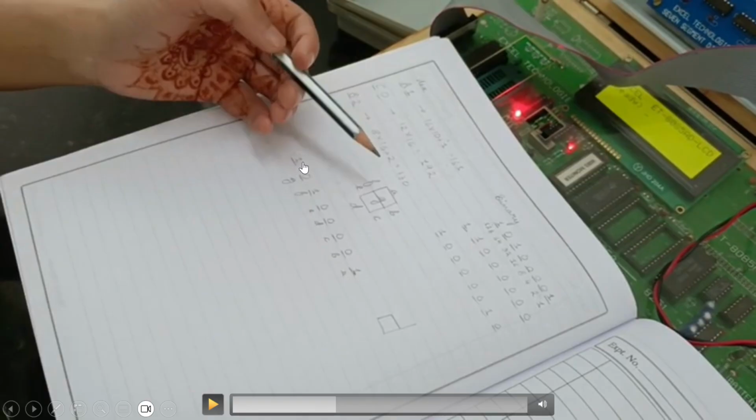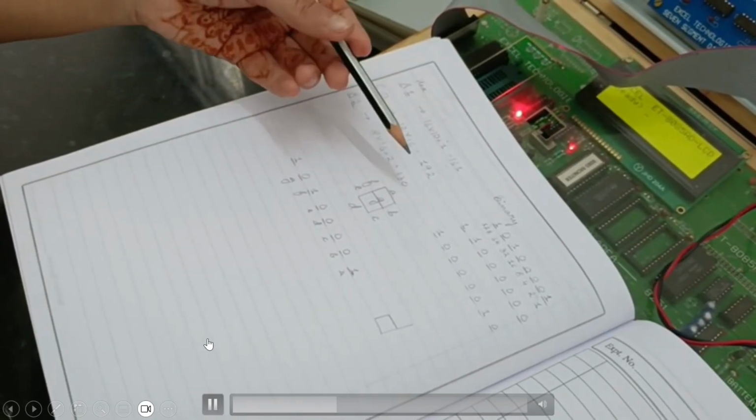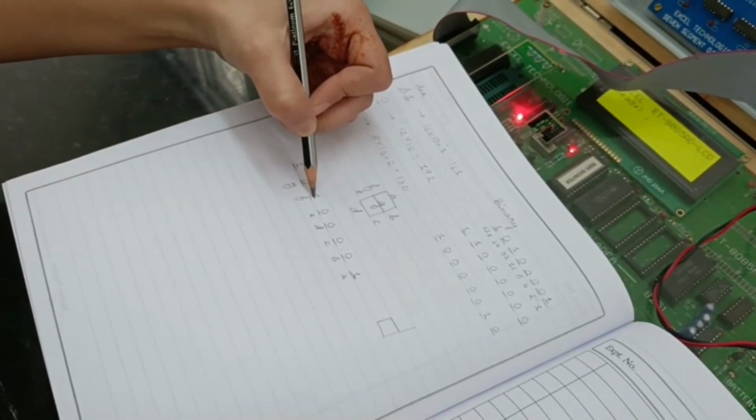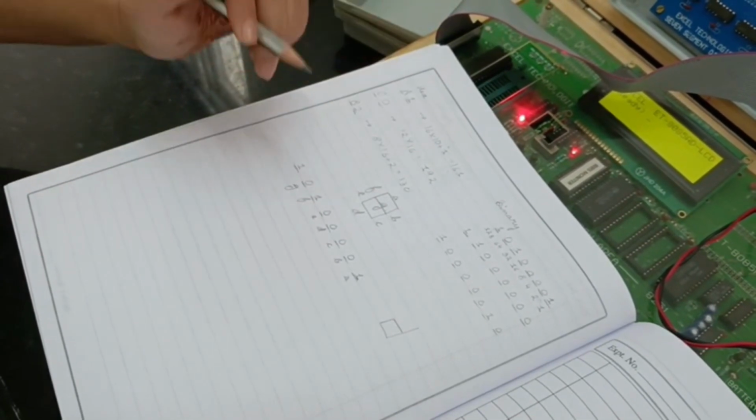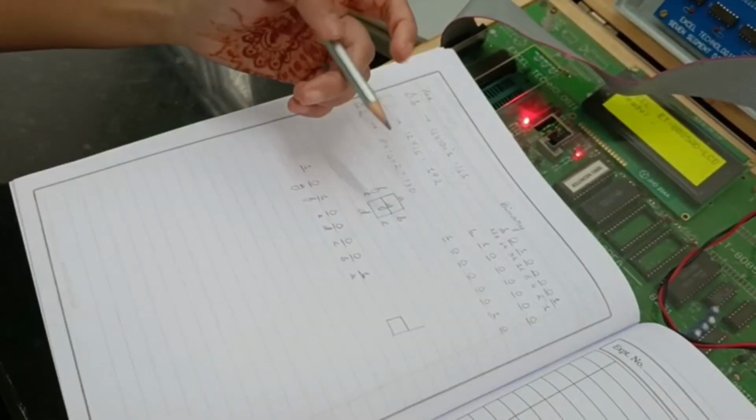The last one, or the most significant bit here, is for the decimal point, which we are not using for this activity. So whichever part you do not use, you give it a 1. The part which you want to use, that you give a 0. This is why the first bit here is 1. For this experiment, when I enter 1 for a particular place, then it turns off that line, and when I enter 0, then it turns on that LED.